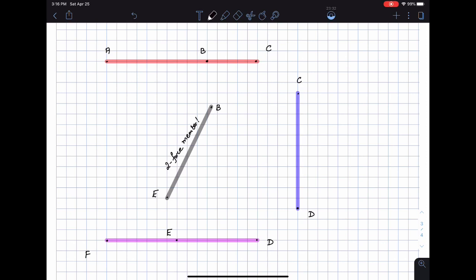Which means that for the bar BE, I'm going to assume this to be in a state of compression, so I'm going to have force FBE, which I'm going to draw this way. So this is the force FBE, and then here is the force FBE as well, of course along the line joining the points B and E. I'm just going to label this as FBE.